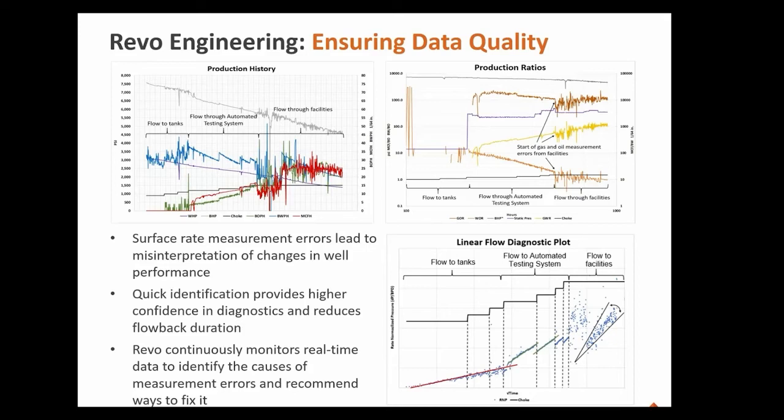Now finally, the bit of data on the end here that's really noisy, I tell you, I'm guilty of this. You get a cloud of data here and you just kind of match a line through it as best you can. Well, the problem with that is 5 engineers will all get something different. And if you're iterating your completion design on the order of 5 to 10% changes in proppant per foot, cluster spacing, anything like that, it's going to be really difficult to distinguish any type of benefit when all your engineers are coming up with slightly different answers. So we need to have really good quality data to be able to do drawdown optimization and assess the completion design.